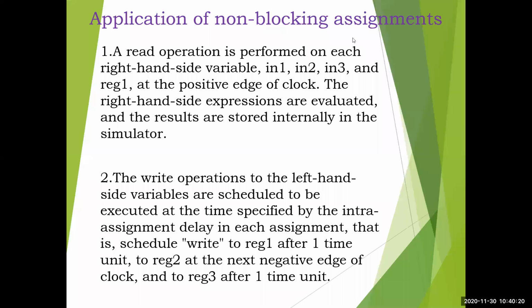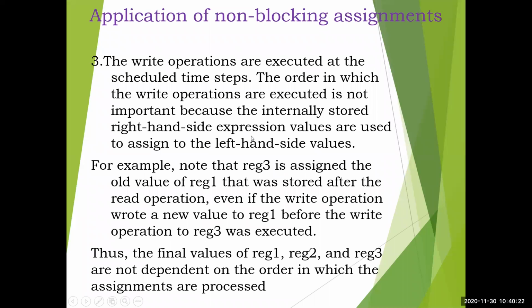Then the third step: the write operations are executed at the scheduled time steps. The order in which the write operations are executed is not important, because the internally stored right hand side expression values are used to assign to the left hand side variables. Based on their internal computation time, it will be assigned. For example, note that register 3 is the last one, assigned the old value of register 1. So the first statement is register 1 equals in 1.